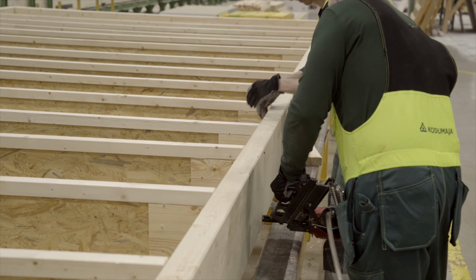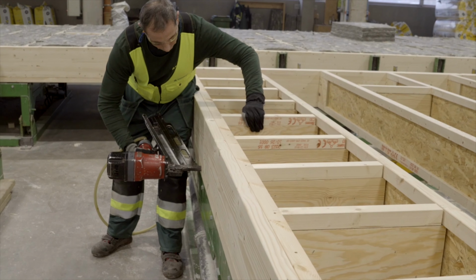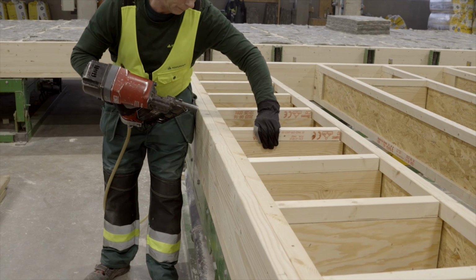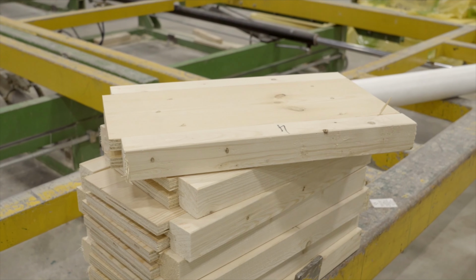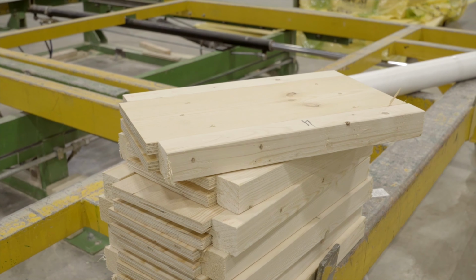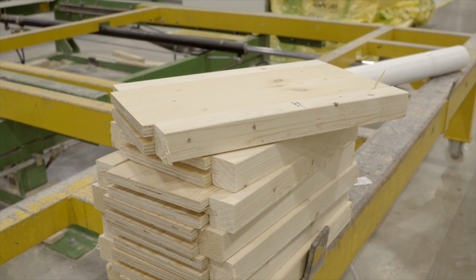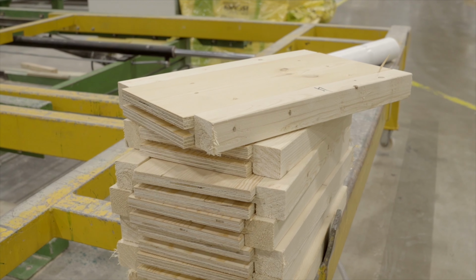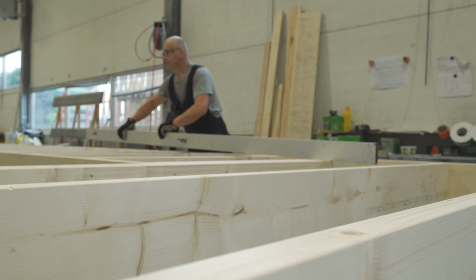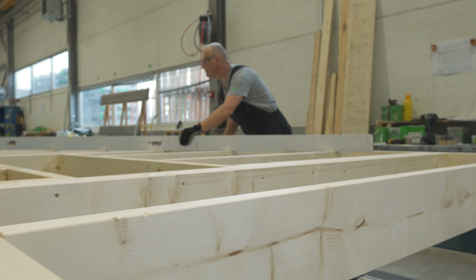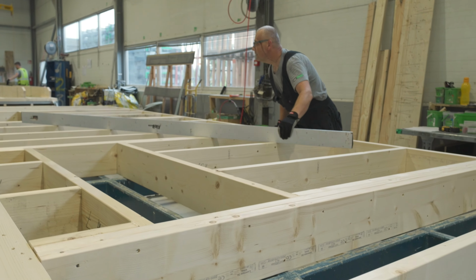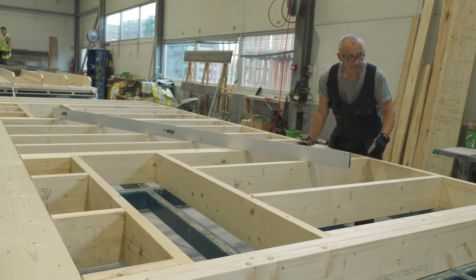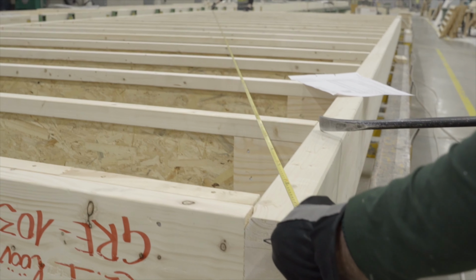must be followed. Depending on a project, reinforcement boards can be attached to the intermediate beams. Reinforcement boards are special wooden components made from plywood or other strong wooden-based material to make beams stronger and more rigid. And the last step for assembling the frame is to check the flatness of the entire construction with a straight edge. There should be no steps at the joints.